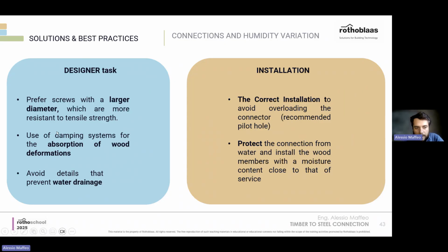We can also add damping systems, so a buffer, a compression material to absorb some compression. This is already being done when someone has a structure completely outside, exposed to the weather. Sometimes designers already specify a few millimeters layer of resilient material, like a rubber material or an EPDM material, to take some of this compression.